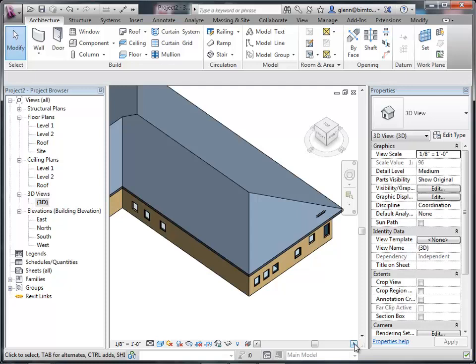As far as the building methodology, this should be something that we can build relatively simply, just by hand. We'd have the students go out there and build it. So we're thinking a simple concrete slab. The walls could be some sort of light frame wood construction, with a little bit of insulation in there. The roof will probably be 2x8 or 2x10 rafters. You won't have huge spans, the building's just not big enough to need gigantic spans with a lot of steel or something like that. It's going to be a pretty simple framing job.